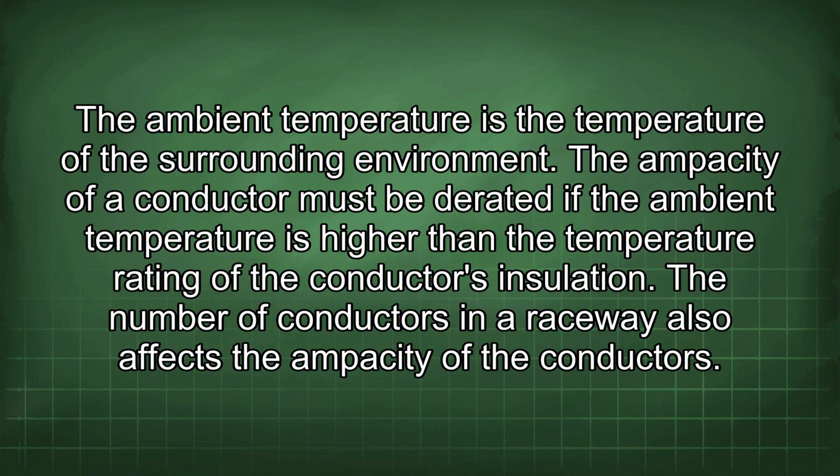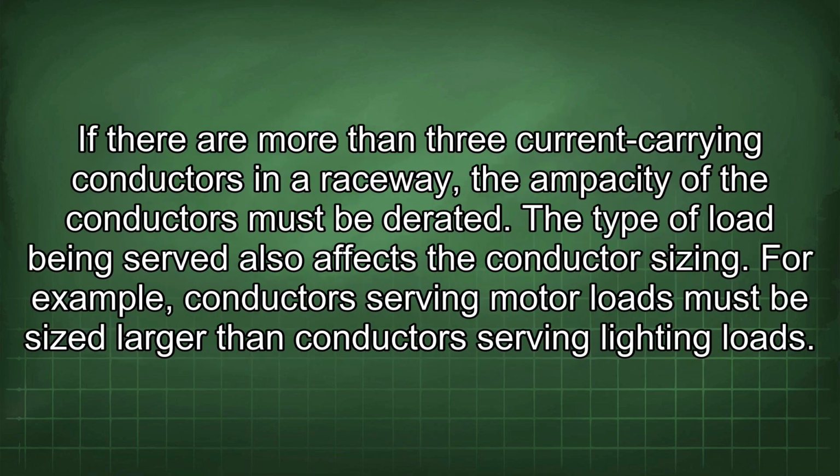The ampacity of a conductor must be derated if the ambient temperature is higher than the temperature rating of the conductor's insulation. The number of conductors in a raceway also affects the ampacity of the conductors. If there are more than 3 current-carrying conductors in a raceway, the ampacity of the conductors must be derated. The type of load being served also affects the conductor sizing. For example, conductors serving motor loads must be sized larger than conductors serving lighting loads.